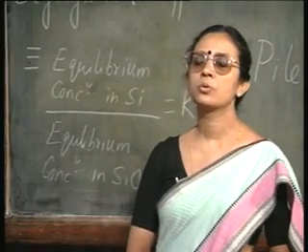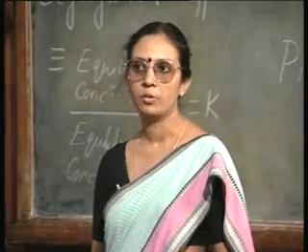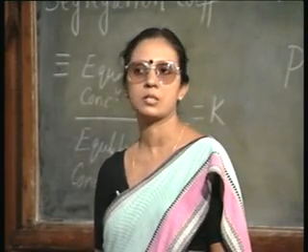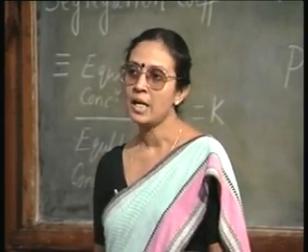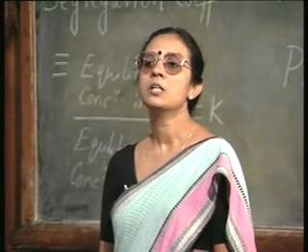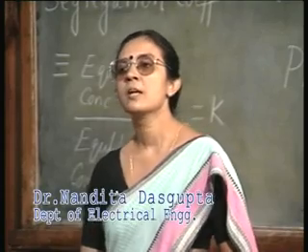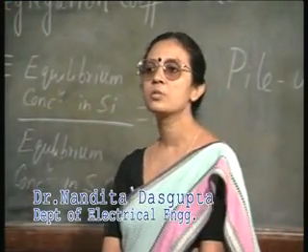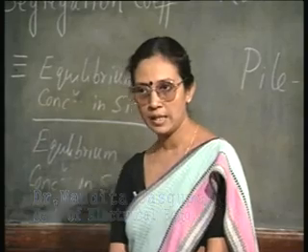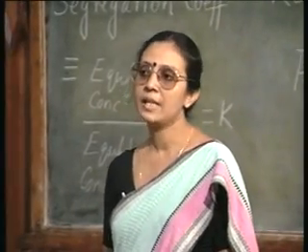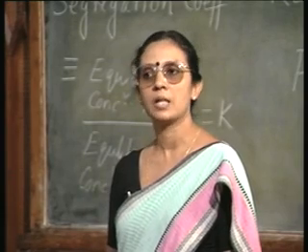Usually, if you are going to grow a thick oxide for masking purposes, say 5000 angstrom or 6000 angstrom or thicker than that, then we use a dry-wet-dry sequence. That is, first for 10 minutes you carry out dry oxidation, then you carry out wet oxidation for whatever time duration, then you follow it up again with a dry oxidation.